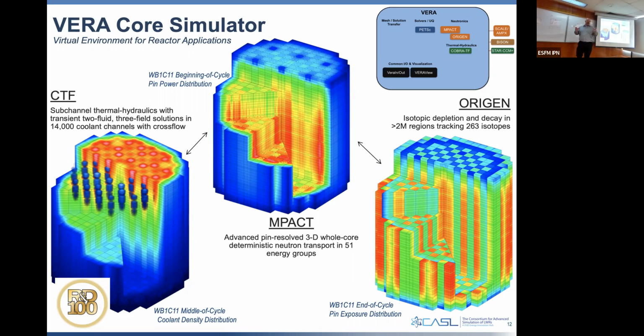So if you're only modeling 1/4 of the reactor, you have 14,000 individual channels. All of those channels can have cross flow between them. And all of the grid spacers are put together in full detail. So that thermal hydraulics capability was developed and tested, compared with a whole suite of benchmarks and experiments.